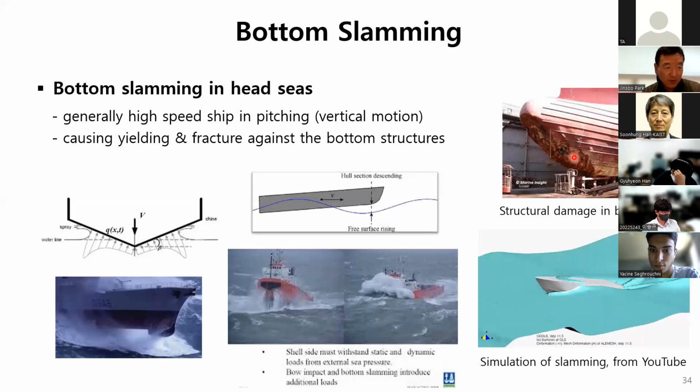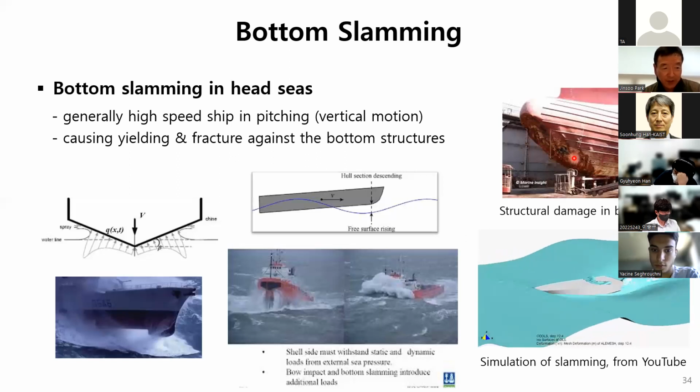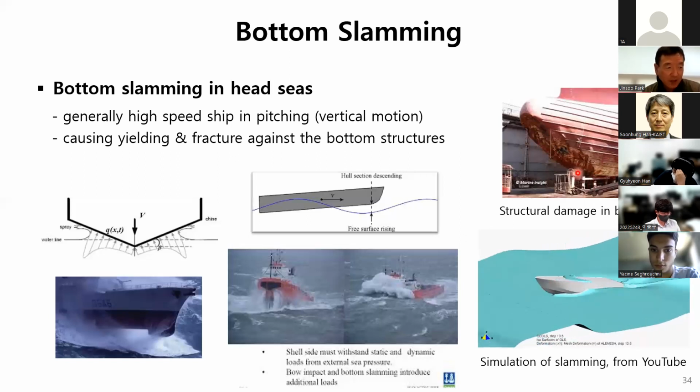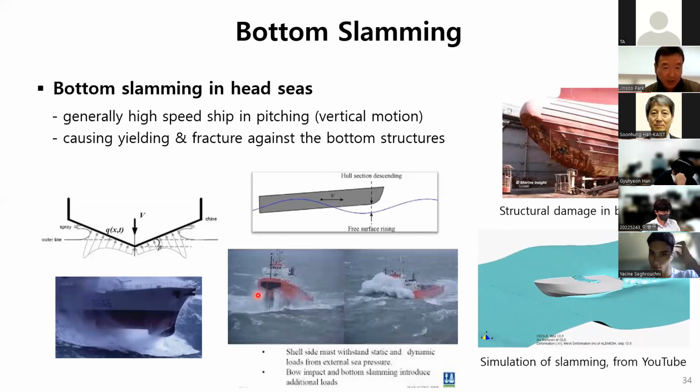Even the bow flare impact and bottom slamming, local loading also induces another type of high frequency hull girder vibration, so-called whipping, resulting in extra vertical bending moment.